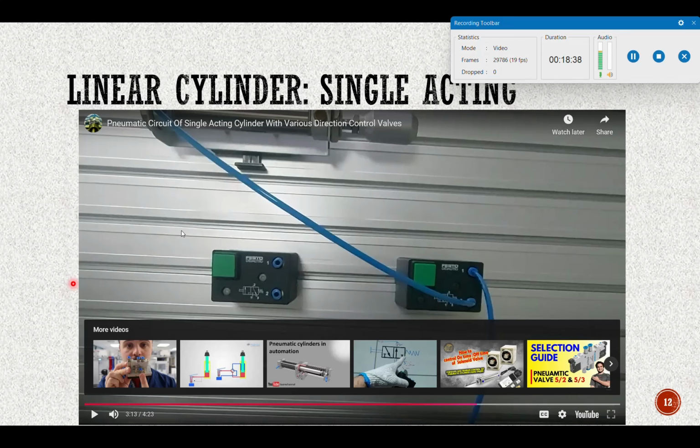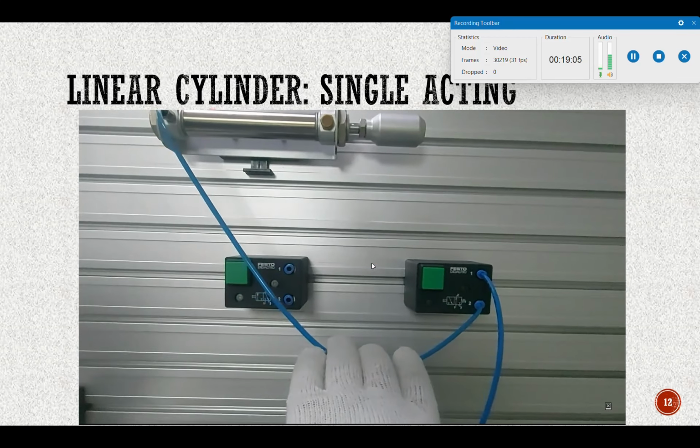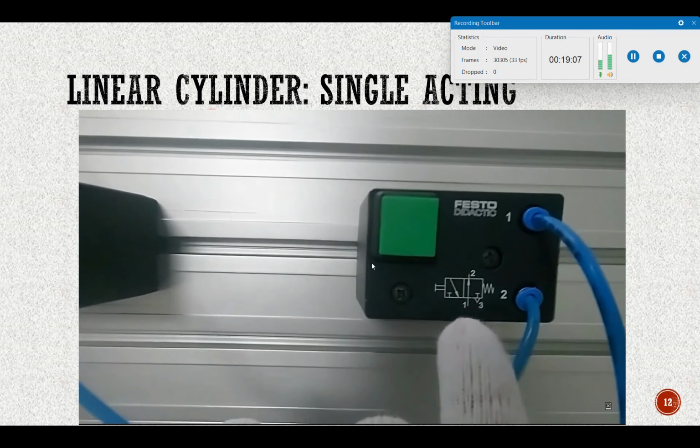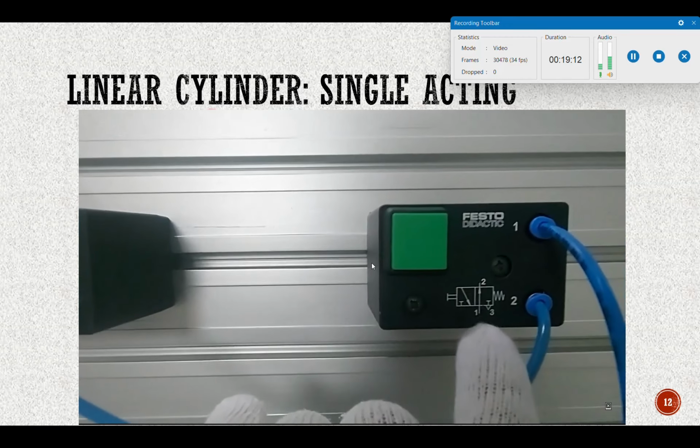But if you use that selector switch, it would hold the state of the valve. That would mean the air would continue pushing the rod to be extended until you change it. Both of them are direction control valves. If you look from outside, they look the same, but if you go into detail and look at the circuit diagram, you will see the difference. So what's the difference?